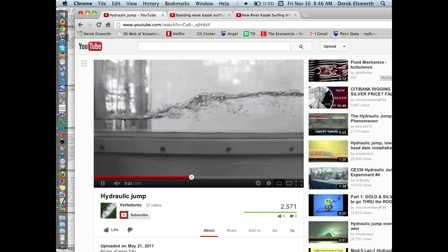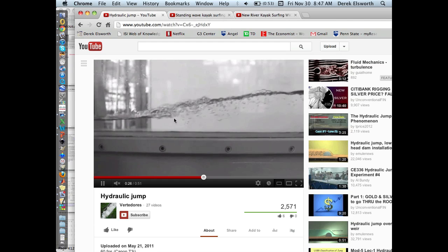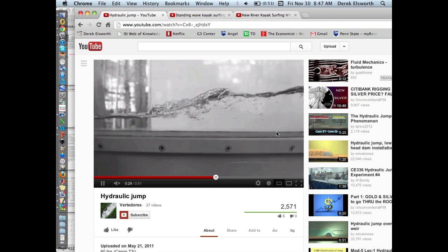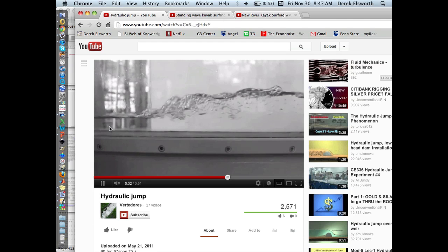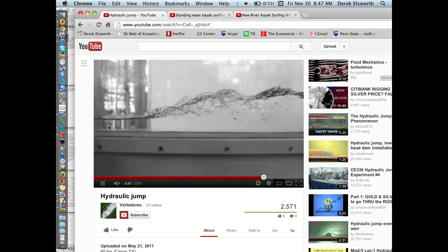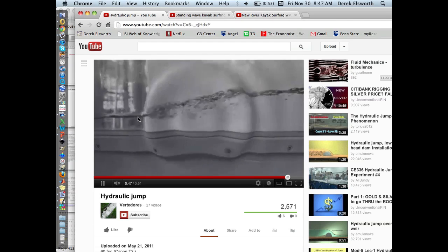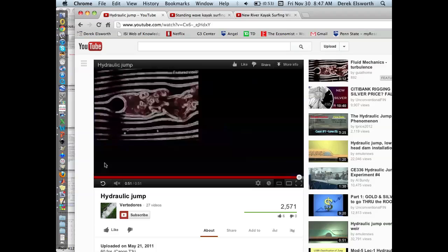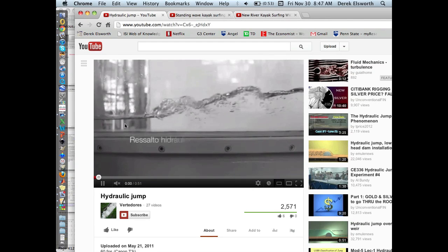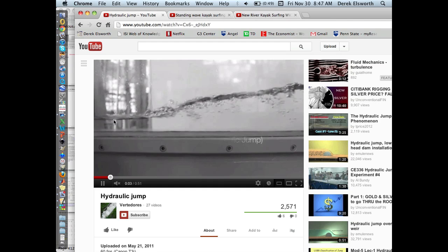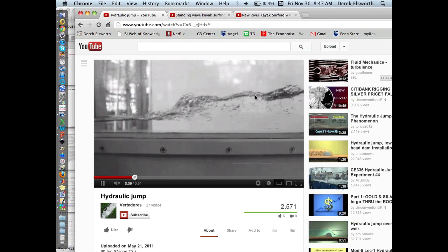And so if you multiply the cross-sectional area of flow here times the velocity and equate it to the cross-sectional area of flow here times the velocity, then by definition the flow velocity here has to be much larger than this by the ratio of these two heights, right? So the question is, why is that occurring, that it can flow in that particular way? It turns out that because it has this extra degree of freedom, it can flow either quickly at a very shallow depth, or it can travel very slowly at a much deeper depth. It can choose either one of those equally well.